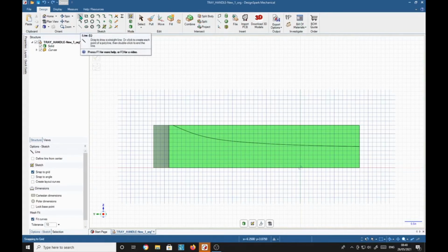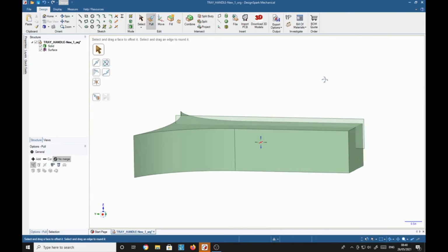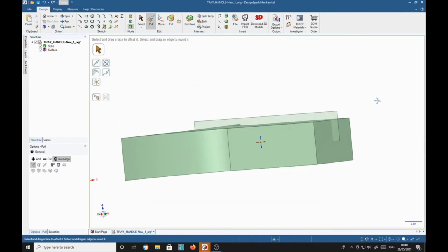You can select it, or you can just type L on the keyboard to get that, and we complete it by going to the very end and up to and along, down, and then if we press the P key for pull, we see we've got a surface which is shown here on the structure panel, structure tree, running down the center of the part, embedded in the part.